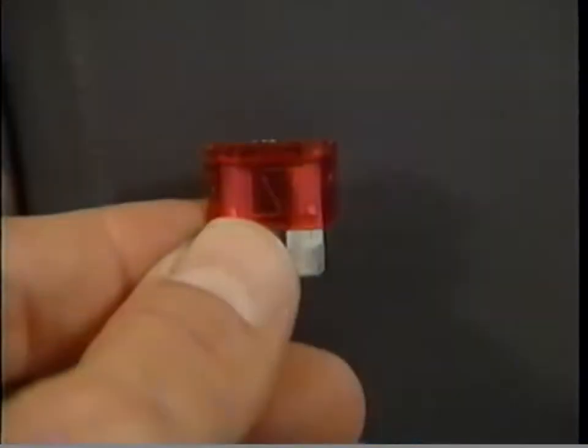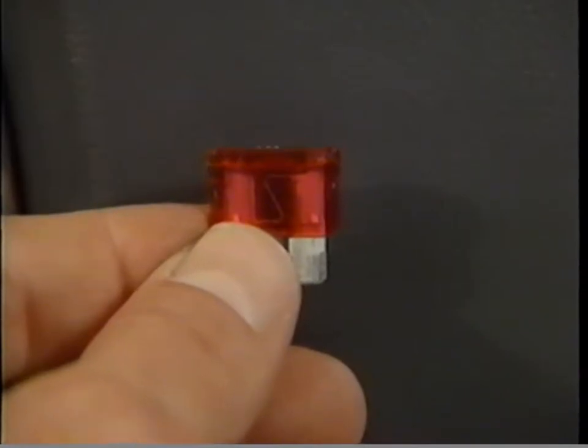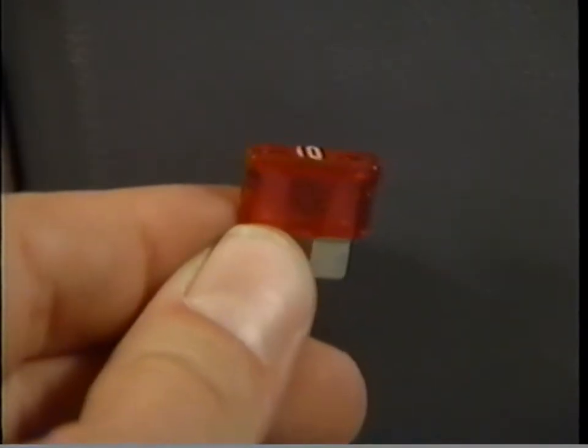On an Infinity 1 and 2 sound system, I found that if the fuse for the amplifier ever opens, I would still receive sound from the tweeters. Well, that's because it's a bi-amplified system, and there are separate fuses. You should always check your wiring diagram to be sure you've checked all the fuses. Checking the fuses, we find that they both are okay.